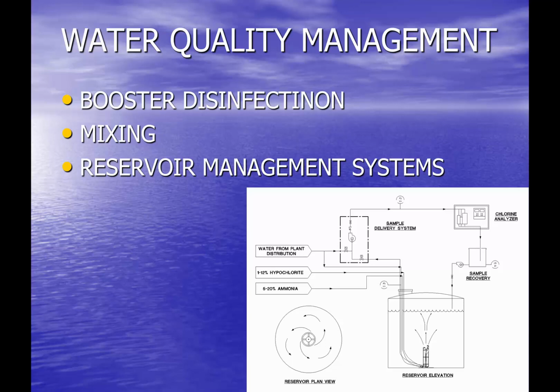And what you have in that case, not only do you have your chloramine injection, not only do you have your mixer, but you have a chlorine analyzer that's dosing the water based on what the actual residual is. So now we're able to set it up with a set point that says, okay, we want to maintain a 2 milligram per liter residual in this reservoir.